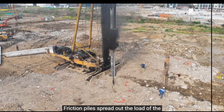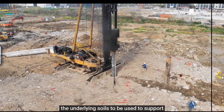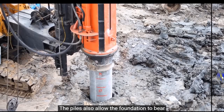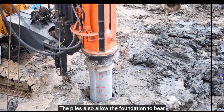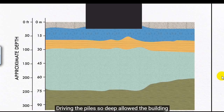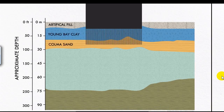Friction piles spread out the load of the building vertically, allowing much more of the underlying soils to be used to support the structure without becoming overwhelmed. The piles also allow the foundation to bear on stronger soils than those at the surface. Driving the piles so deep allowed the building to not sit on the surface layer of artificial fill or even the soft underlying layer of mud, but rather on the dense, sandy soil of the Colma Formation below.